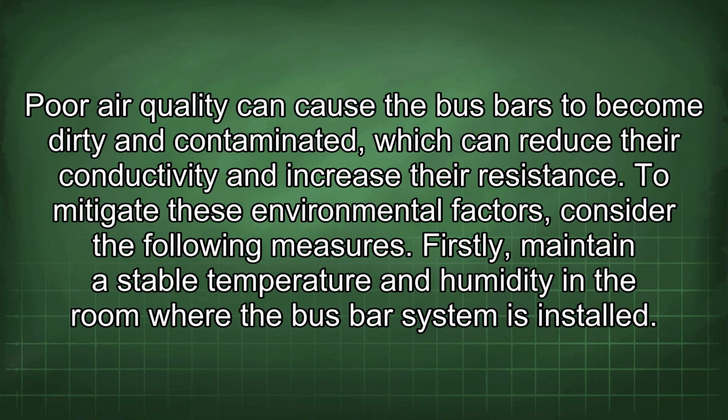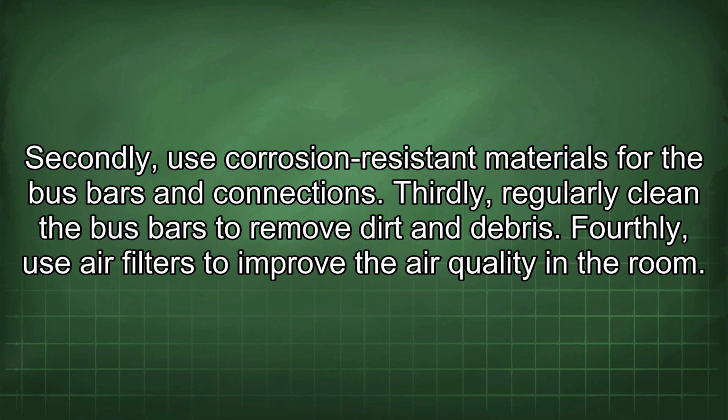Firstly, maintain a stable temperature and humidity in the room where the busbar system is installed. Secondly, use corrosion-resistant materials for the busbars and connections. Thirdly, regularly clean the busbars to remove dirt and debris. Fourthly, use air filters to improve the air quality in the room.